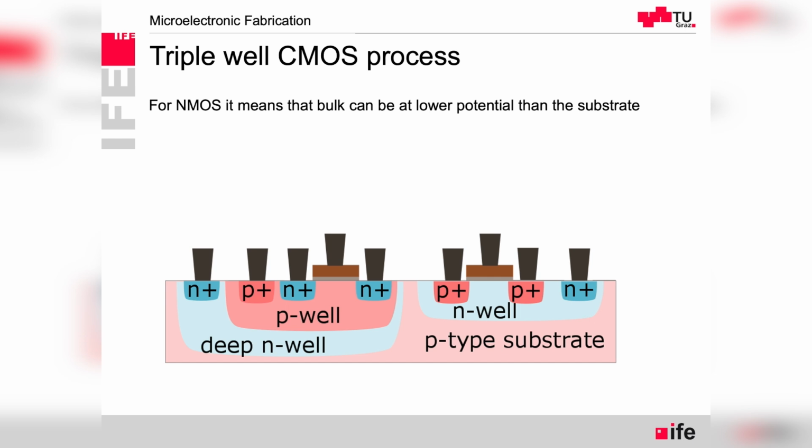then the P-channel transistor is done as usual with N-well diffused into the substrate. But for the N-channel transistor, we have a deep N-well that goes maybe 2 micrometers into the substrate. Then we have a shallow P-well, and in this P-well we have the N-channel transistor. Now if we want to have several N-channel transistors with different bias of the body, then we can connect them to separate potentials, and it's not everything shorted, and also the bulk doesn't have to be at the substrate level. So we have the isolated diodes.